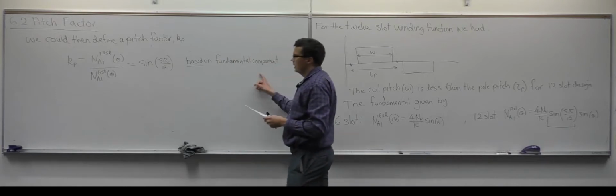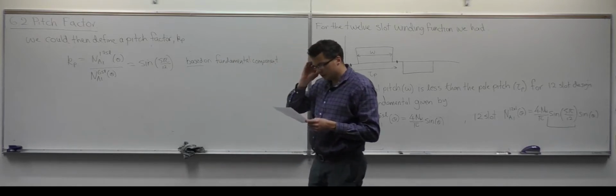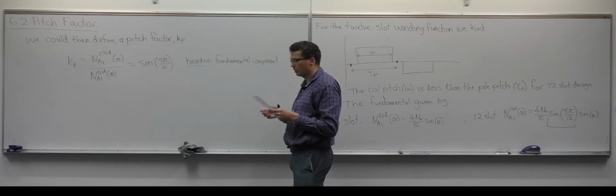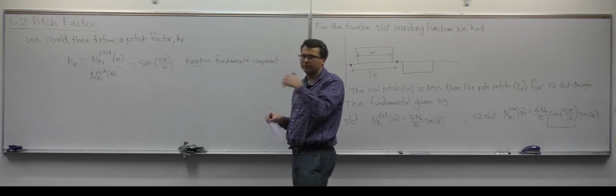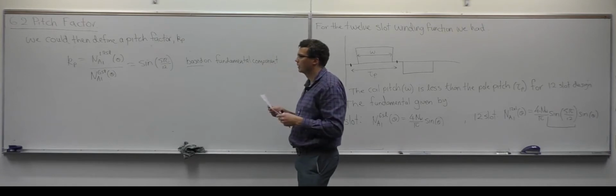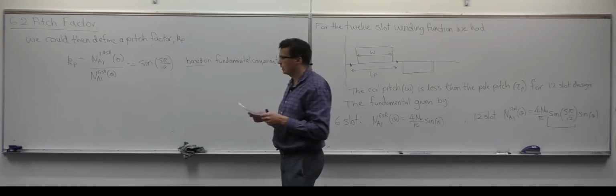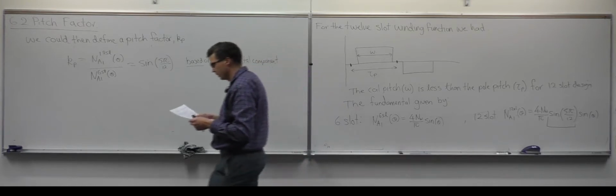So it turns out then that for the general case, the pitch factor can be calculated from looking at the fundamental field going across the pole of the machine. So let's look at that in a little bit more detail.